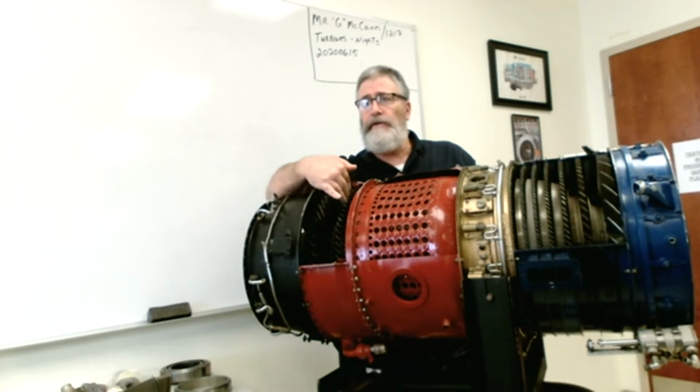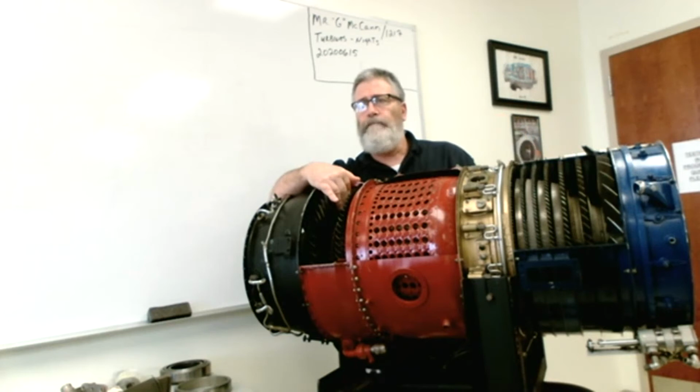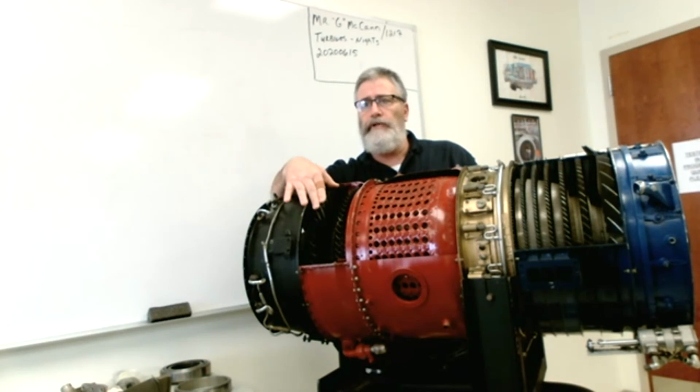We do have a nozzle in between each turbine stage, just the way we had a stator in between each compressor stage, all right? Some engines just utilize 1 turbine. Some use multiple because the exhaust gases are going past, so it's a good way to extract more energy.